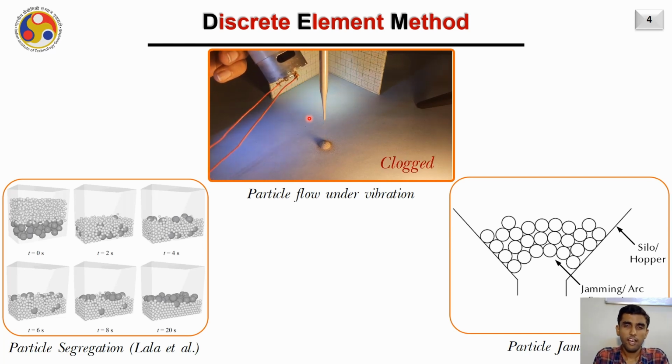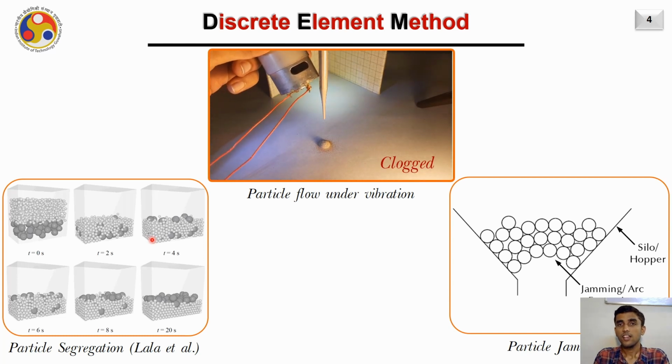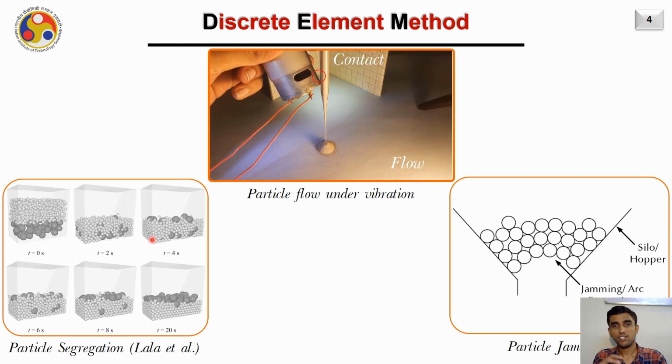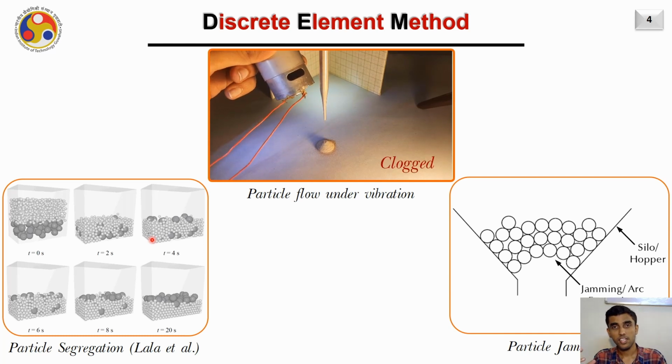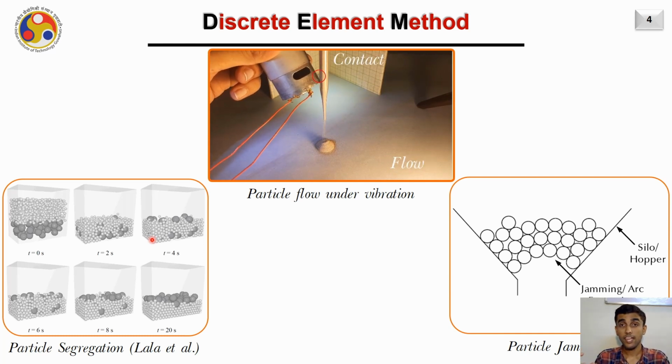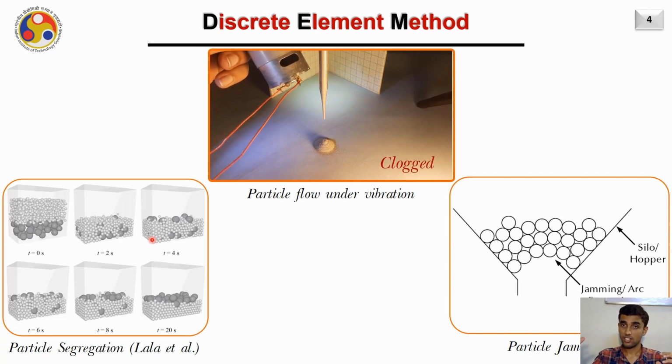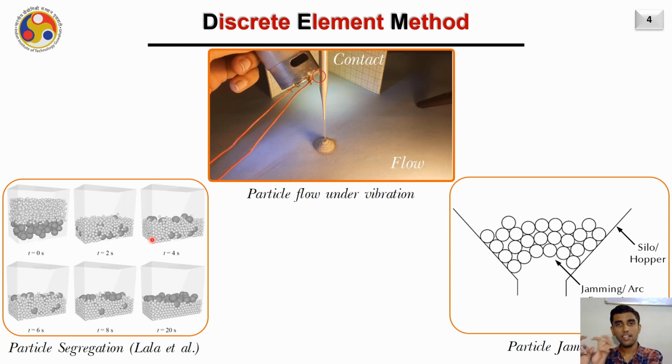One other thing that we have already touched upon for the case of powder segregation is in the context of mixed powders for selective laser sintering. As you already know, in mixed powders we have the structural powders or the structural material, and then we have the binder materials. So these are two different powders. One is for the structural element, and the other is to bind these structural elements together.